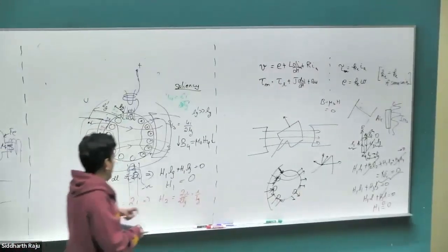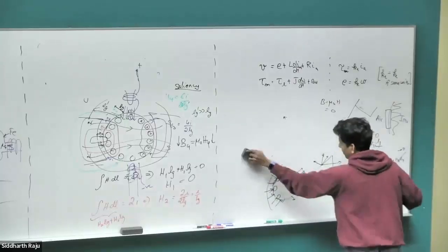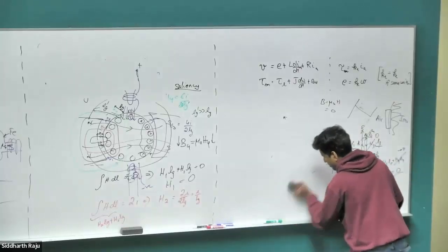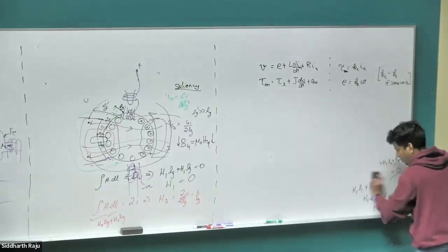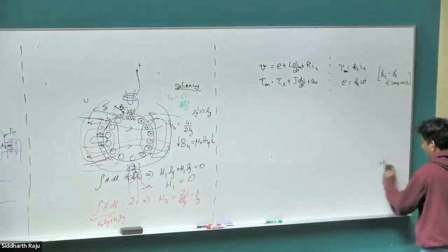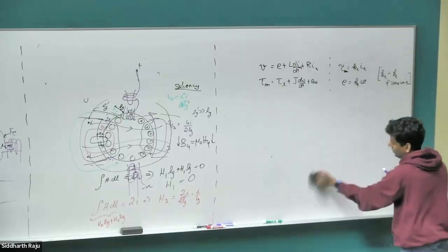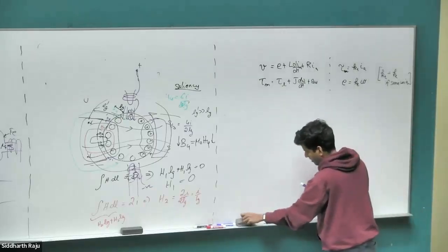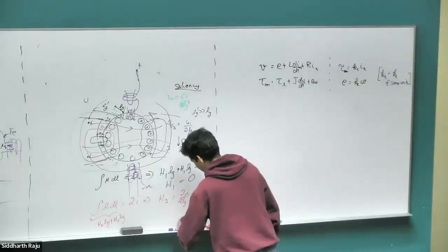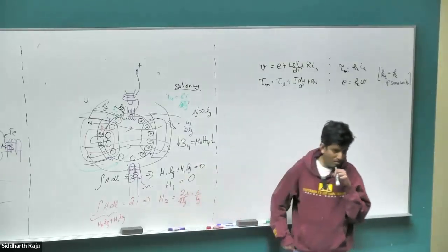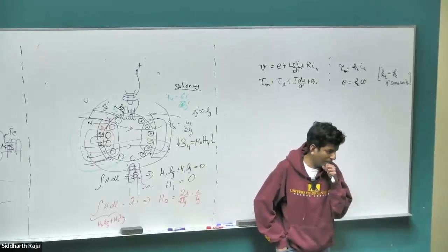where we wanted to get the field there as low as possible during the commutation instant, so that the EMF built up across it is as close to zero as possible. Is it sufficient if the EMF is zero for commutation? What does need to be zero at the 90-degree point?